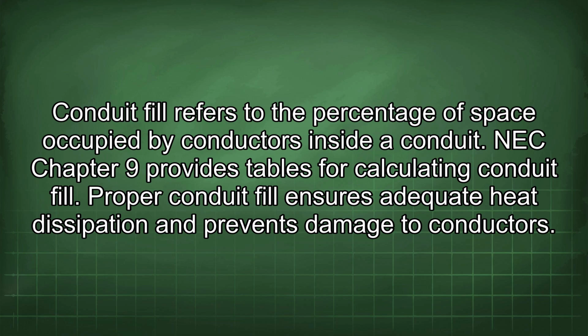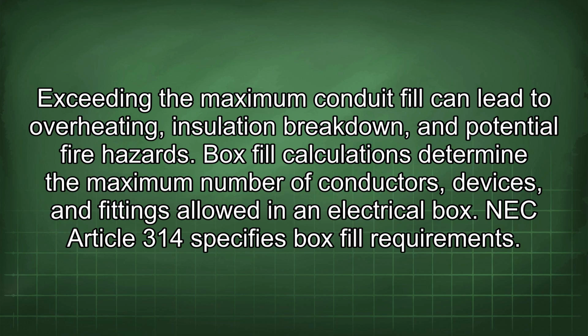Conduit fill refers to the percentage of space occupied by conductors inside a conduit. NEC Chapter 9 provides tables for calculating conduit fill. Proper conduit fill ensures adequate heat dissipation and prevents damage to conductors. Exceeding the maximum conduit fill can lead to overheating, insulation breakdown, and potential fire hazards.